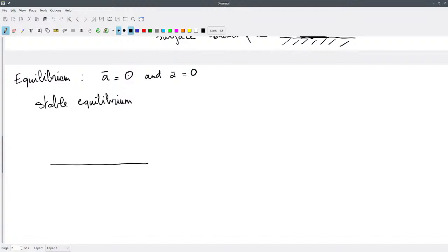So that's an example where we have, for example, a mass, a block, a box that's just lying on a surface, and as I indicated, the normal force will be applying at the effective center of that surface where there's contact, and the weight will be applying at the center of mass of this object, so that will be at the center.